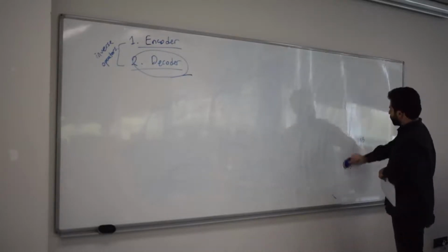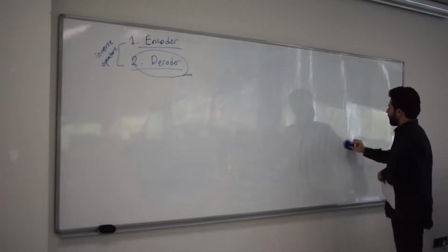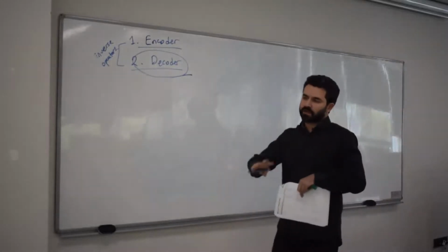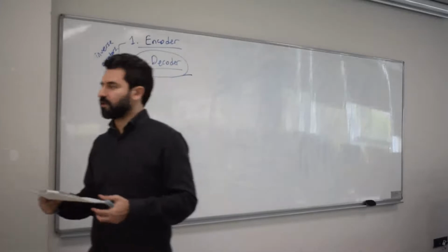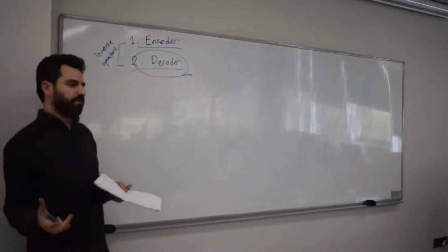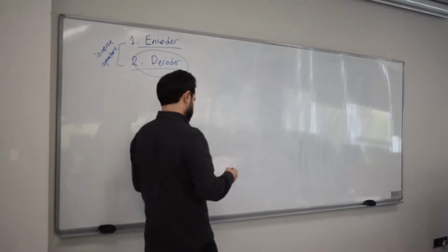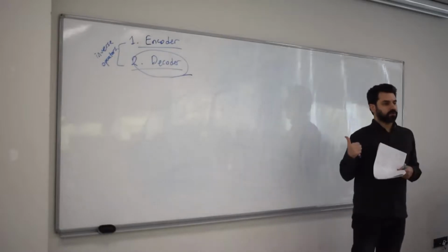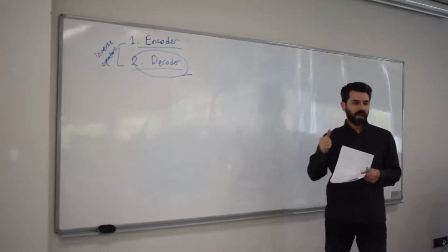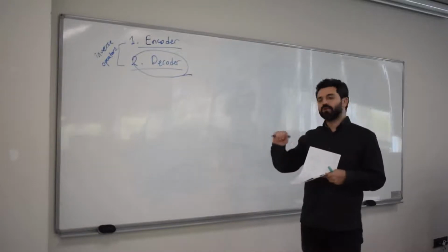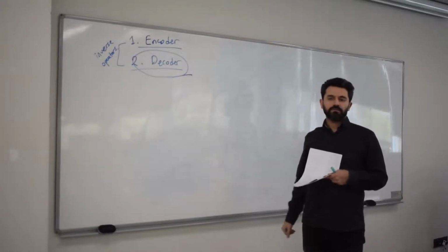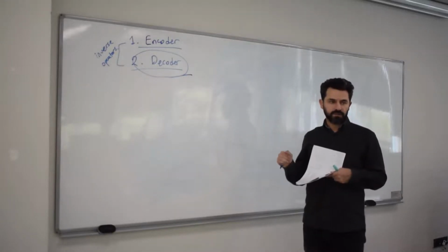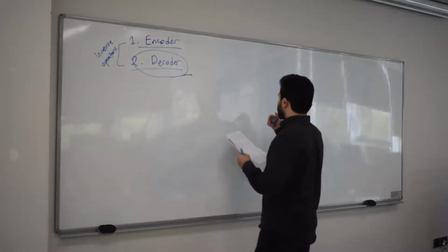Okay, so decoders are pretty useful because they help us implement functions pretty easily, because they give us the min terms. So we collect the min terms to be able to write the function f in terms of SOP form. Then you use a decoder to implement it. Okay, one more thing about encoder and decoder, both of them, is the enable input, that you may have seen in your labs. An enable input, basically, when you turn enable on, that means the circuit will operate. If you turn it off, then the circuit will not operate. Okay, that's the idea behind enable.